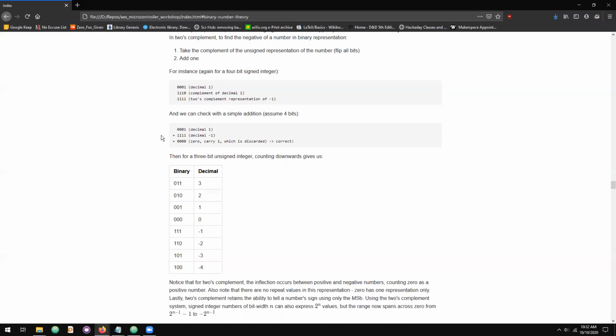And the way we can confirm that is by, again, going through the two's complement method of producing negative numbers, and we just assume that the resolution is 1 more. So if we started with a decimal 1, sign extend out a bit to increase the resolution, so 5 bits total. If we took the complement of that, we'd still see a 1 out here in the most significant bit.